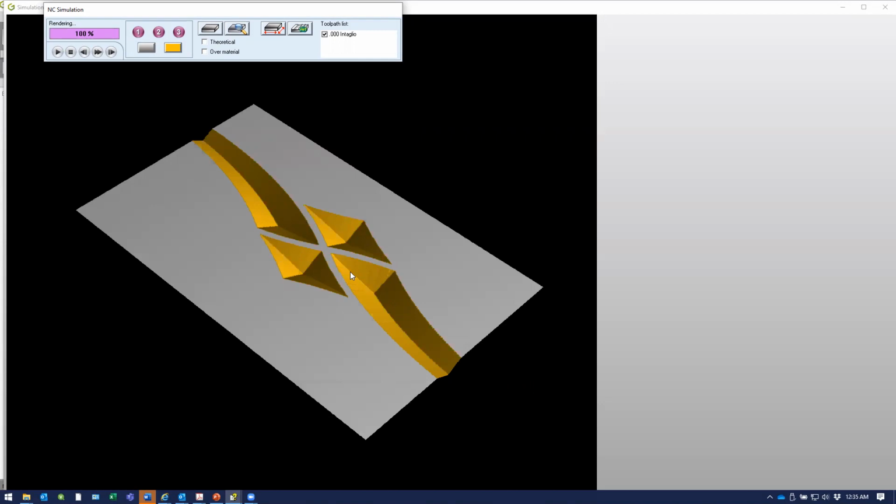So if you don't set your Z to the surface of the material, maybe you set the Z a little above the material, or when you're setting your Z, your cutter pushes into the material, and that's a common thing with foam if you're not careful, then the depth of the cutter would be different than in the rendering. Okay, so that's one way to troubleshoot that.